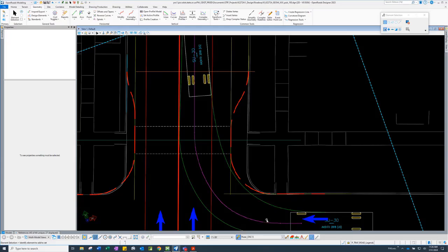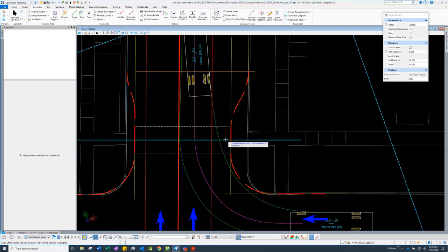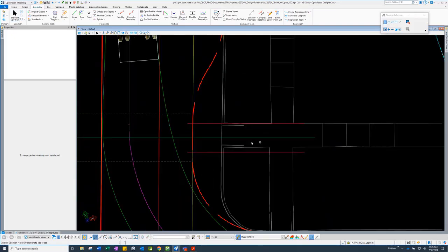And we'll pick 13. No, 13 is dark purple. No, we won't pick that. We'll pick 10. So now we want a 6-foot wide ramp right here, right? Well, I have my center line. I again set, nope, 3, my bad. I will set a line up and I will take it back, maybe back to here, because this is the path, the pedestrian path, in how my brain works. And I will say, yes, I want to mirror it. So now I have 6 feet wide, right? I can offset, I don't think I have it set up for top back of curb.